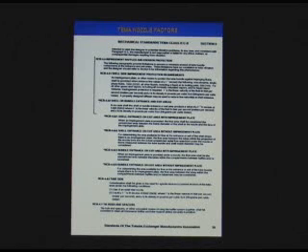This is basically the term rho v squared, density times the velocity squared. 1500 is the typical limit, or where we would impose the installation of an impingement plate. What that does is that takes the energy of the incoming process stream and diverts it horizontally so that it enters the tube bundle with minimal potential for causing the tubes to vibrate.